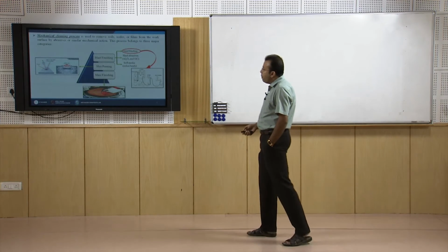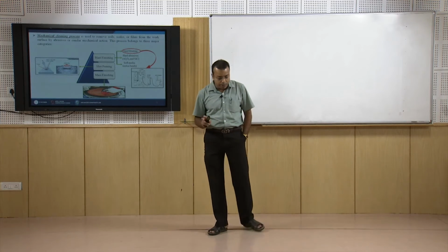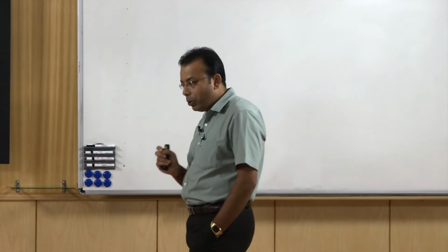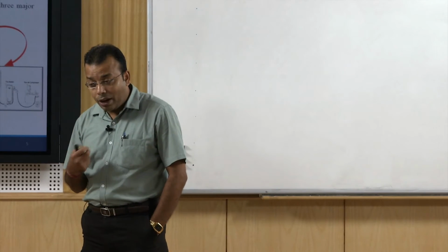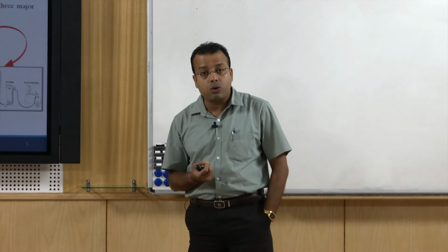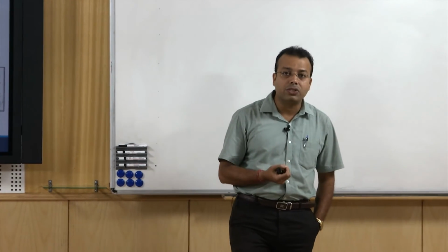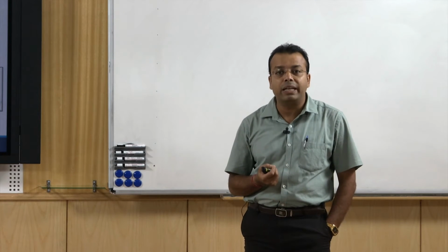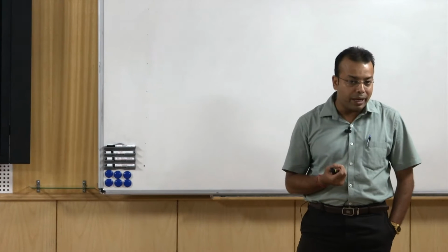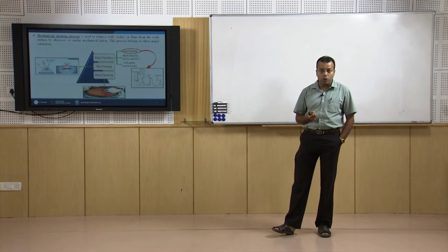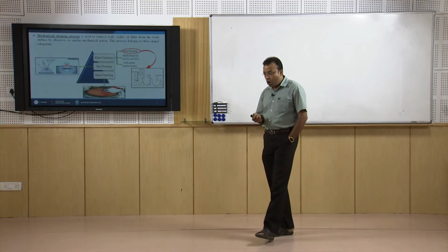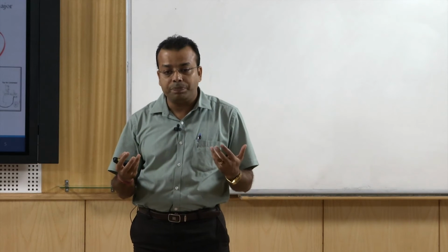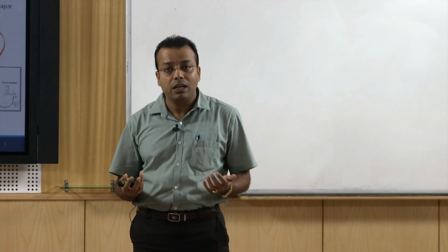Next we will discuss the mechanical cleaning process. Till now we have been discussing the chemical cleaning process, where we use certain chemical materials and allow the material to undergo chemical reactions with the solvent itself. But in this particular slide we are going to discuss mechanical cleaning. That means we are applying some kind of energy, in terms of pressure or load, or any kind of erosion or abrasion onto the material surface, by which the outer surface gets cleaned.